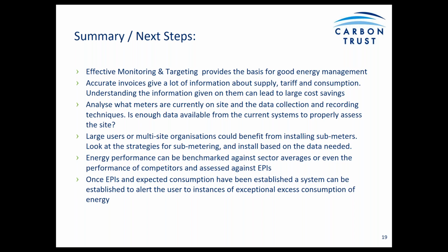So as a next step, it's important to analyse what metering arrangement is currently at site and what data collection and recording processes are currently in place to measure and record the data that is available from the meters. It's also worth asking the question of, is enough data available from the current metering system to be able to properly assess the energy consumption at the site, or would the site benefit from more advanced metering?